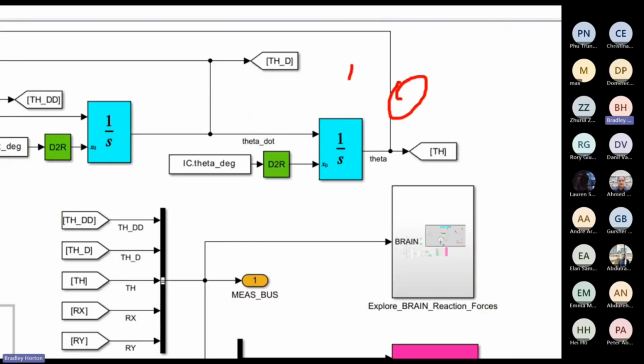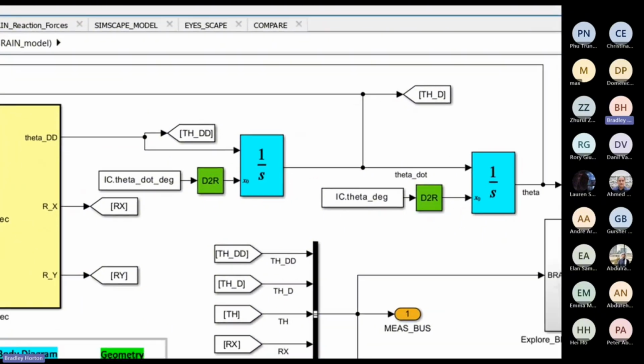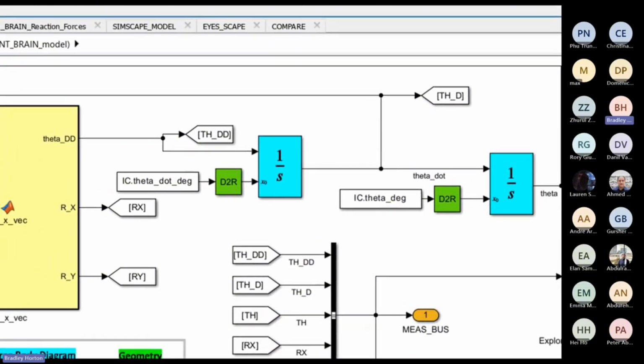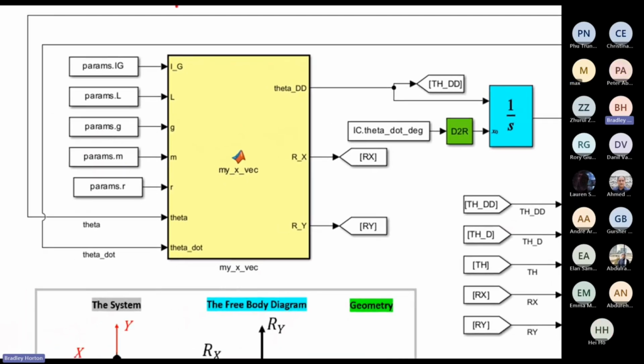So these integrator blocks are at the very heart of how Simulink is able to numerically solve nonlinear ODEs. And yes, you're exactly right that it kind of looks like there's a feedback mechanism in the way that it does that, because if you follow the signal wires coming out of those integrators, you'll see that they're making their way back into the little yellow block.